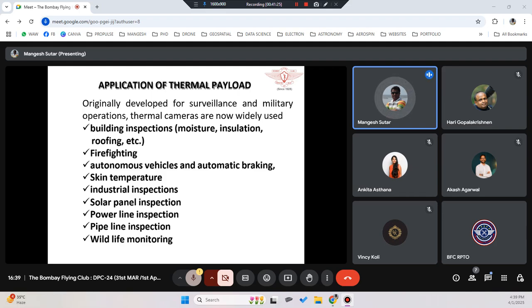It was bound that over a period of time that corrosion would increase and there would be a leakage in those pipes. So that's how we were able to come to know, which was not visible to our normal RGB cameras, but was because of the thermal sensing. It was able to tell us where we have the problems.